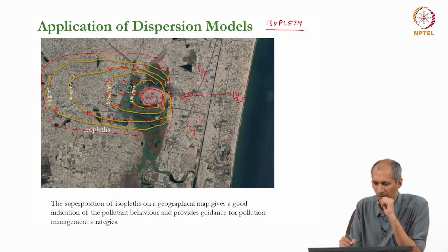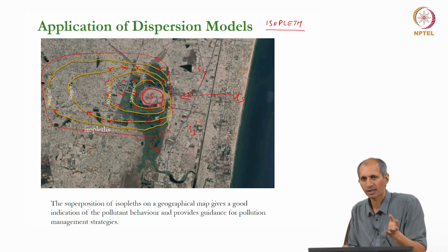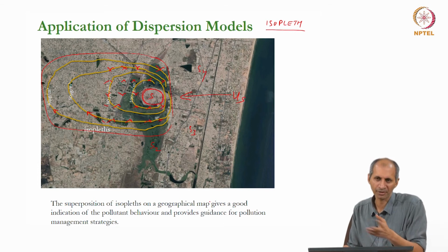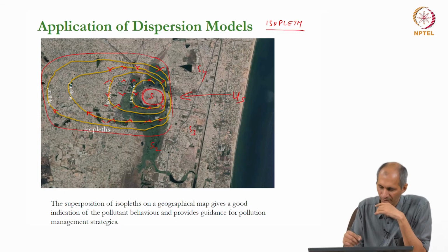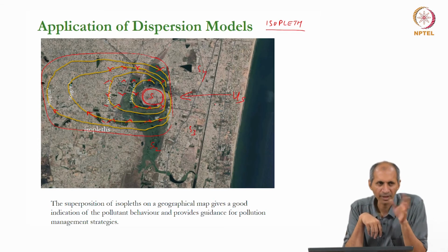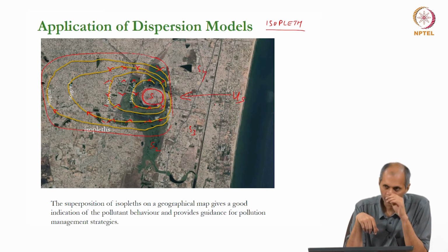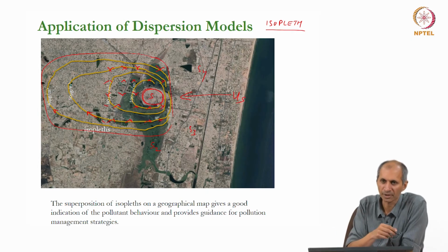So even if they are burning coal in all these 4 places, the emission factor for sulfur dioxide, if they are doing the same process, should be the same, but you still have to estimate it differently for all these 4 sources, because the emission rate is estimated differently based on activity rates and all that. Each of these is done separately, and then you apply the Gaussian dispersion model and plot the contour map.